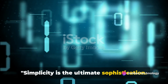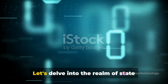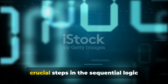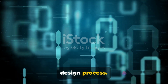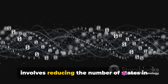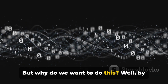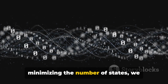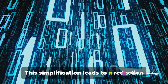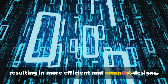Simplicity is the ultimate sophistication. This holds true even in sequential logic design. Let's delve into the realm of state minimization and state assignment, two crucial steps in the sequential logic design process. State minimization, as the name suggests, involves reducing the number of states in a sequential circuit. But why do we want to do this? Well, by minimizing the number of states, we simplify the design. This simplification leads to a reduction in the number of flip-flops required, resulting in more efficient and compact designs.